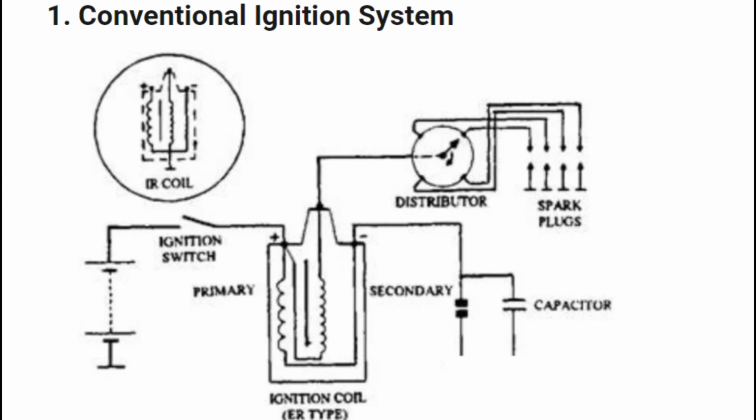The collapsing field crosses the windings of the secondary coil and creates an electrical current in them. The current flows through the distributor cap and finally into the spark plugs in a few seconds. These earlier mechanical distributor systems had their weaknesses. The ignition points would break down and change spark timing, which decreased engine efficiency and caused replacement.